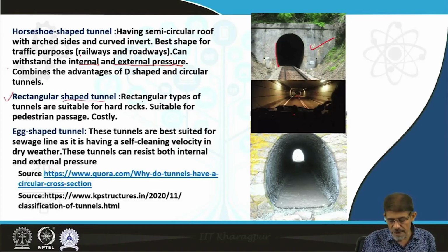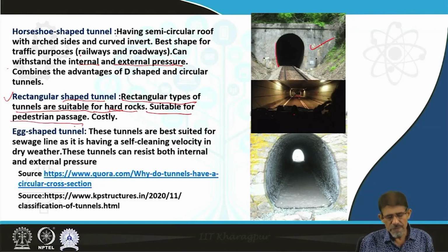Rectangular shaped tunnel, this type of tunnel we have limited in number. The rectangular types of tunnel are suitable for good to excellent quality of rock strata, hard in nature, not going to show any type of failure or inherent damages, and this is suitable for short distances and utilized as a pedestrian passage or pedestrian way.